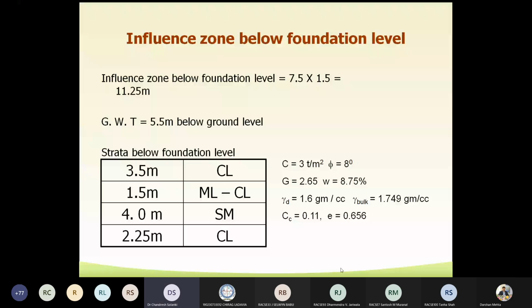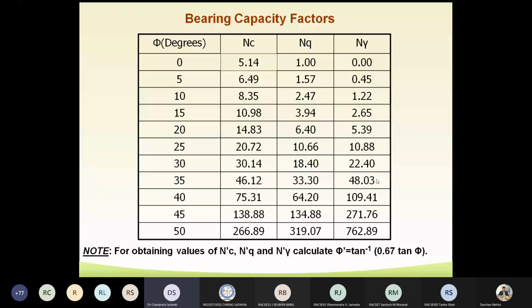As far as this presentation is concerned, the void ratio has significance in classifying the soil as general shear failure or local shear failure as far as the IS codes are concerned. The values of the bearing capacity factors are to be taken from these values using this chart. However, our case is neither local shear failure nor general shear failure. We need to interpolate the results. Interpolation will be required in computing the bearing capacity factors, which will be shown to you here in this computation part.